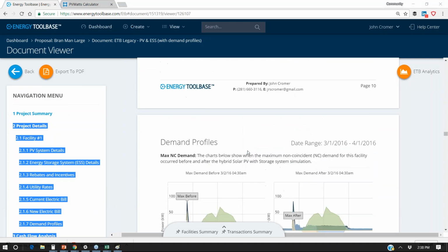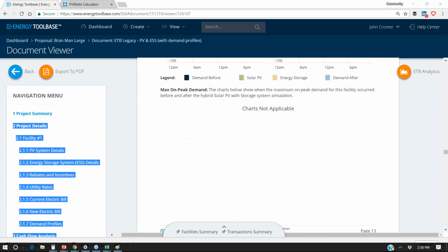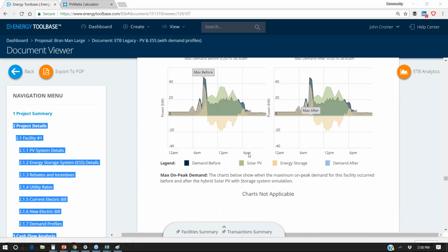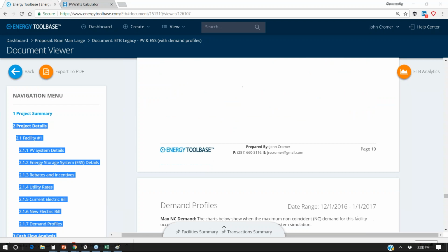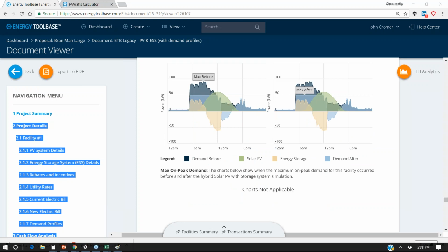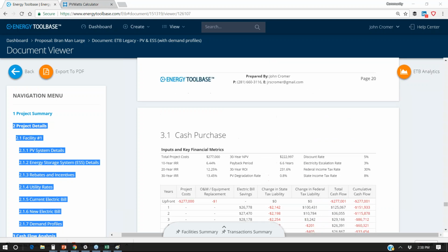And then we go and look at the impact. An energy tool will show you the conditions of every month of the year in its little report. And the problem is, to hone in on this, you have to take a guess on what the best array and battery size is. And then you have to run some more simulations and say, well, what if I increase the battery size? What if I just increase the inverter capacity? What if I just increase my solar array capacity? And then kind of hone in on your optimal configuration that way.